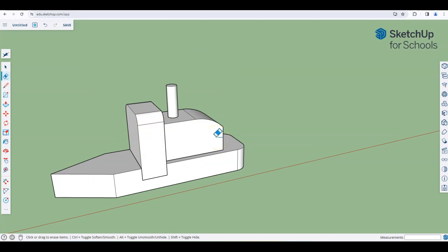As always, you should pause, rewind, and rewatch parts of this video until you can get each piece. But again, I want to go right back to the very first things I talked about, which is to look at an object as its base shapes, start by drawing those, and then adjusting by adding and subtracting from those pieces, either cutting things off or adding things on to change the overall look, to give it detail. Make sure you use components regularly, so every new sort of piece, make it a component. That way you can move things around. If you don't like where it is, it's much easier to move it or even delete it completely if it's already a component. So that's pretty much the process.